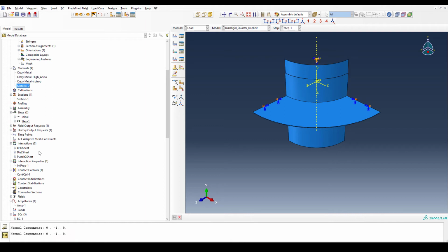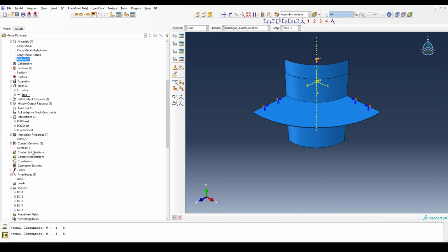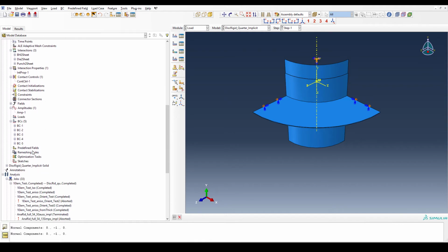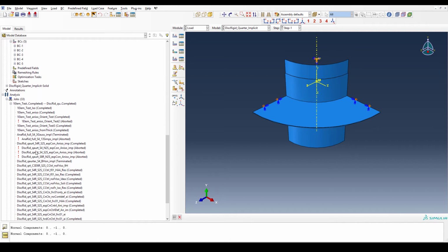dies tend to vibrate, because the forces you apply, or the dies apply on the sheet, are not super high, but the time span over which you apply it is so short that your inertia effects really play a big role in the outcome of your simulation, up to the point where, let's say, your die can also fracture because of the huge impulse technically, right? It's a short amount of time.